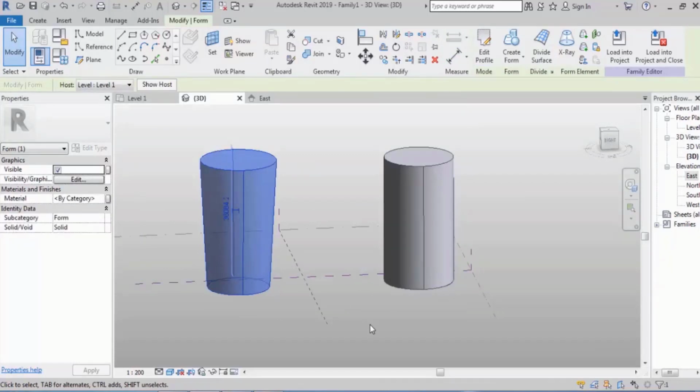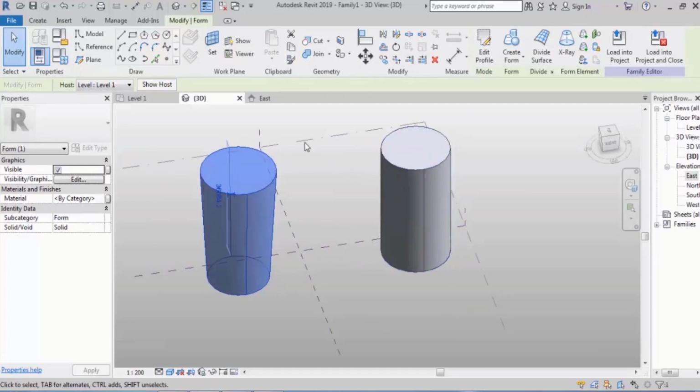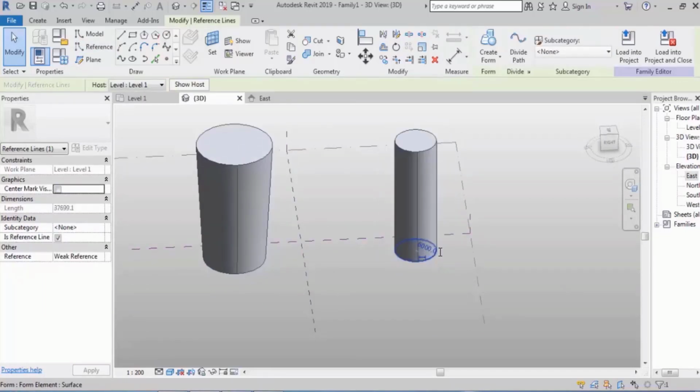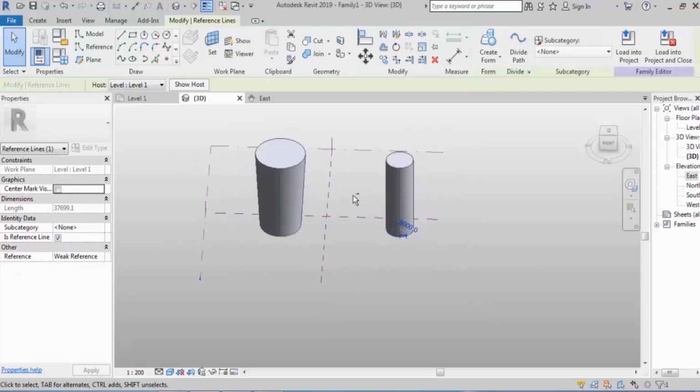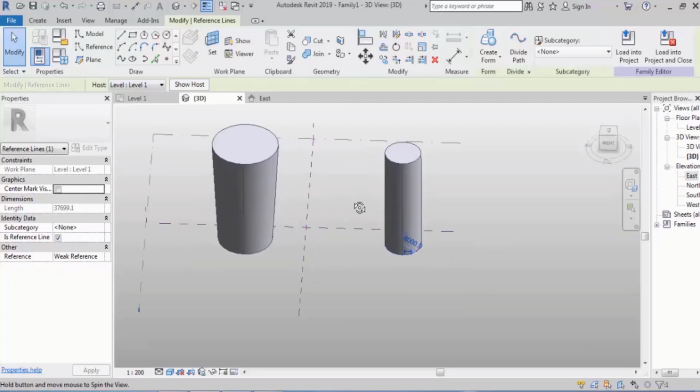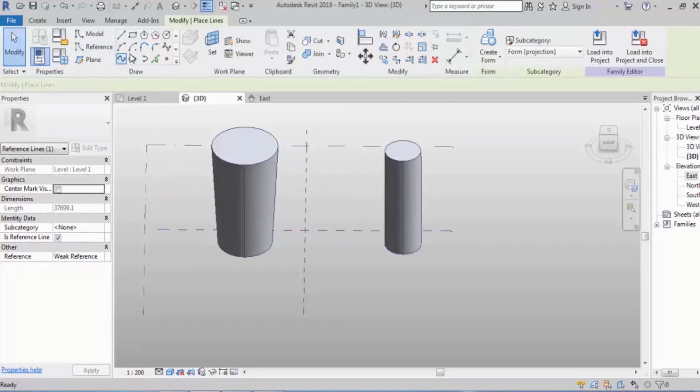This is so useful for creating patterns that when we want to control a form in height, we use reference line. And by changing the base, all that form will be changed. And in the future, we will find it so useful. And the last thing is that when you, for example, use model to design a form, that line will enter the project. By reference line, it won't.